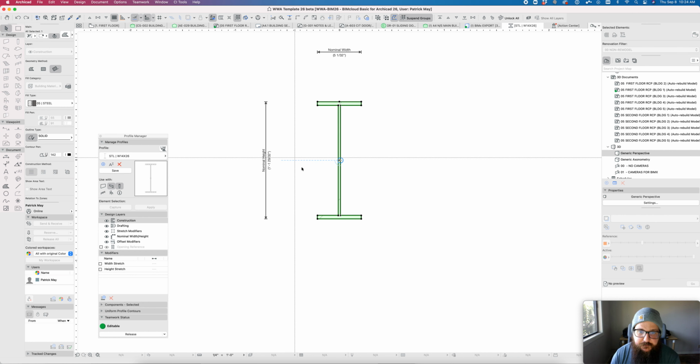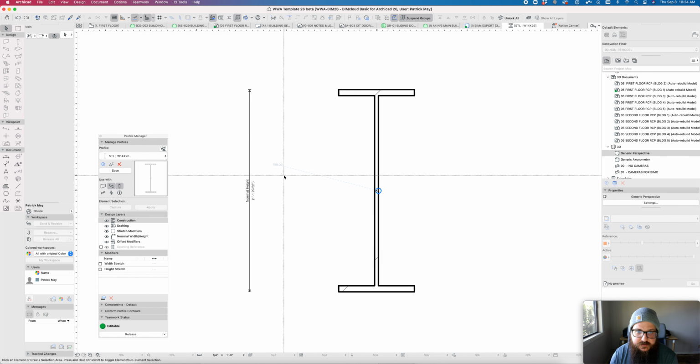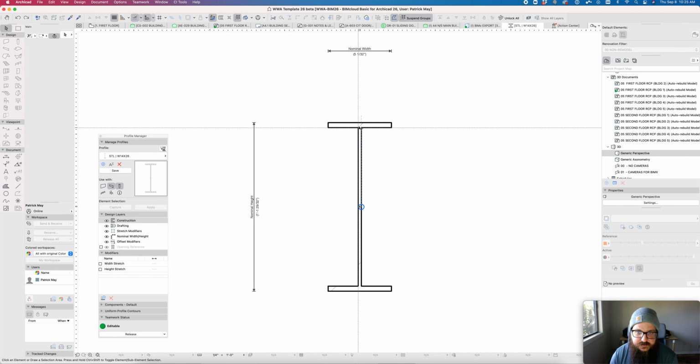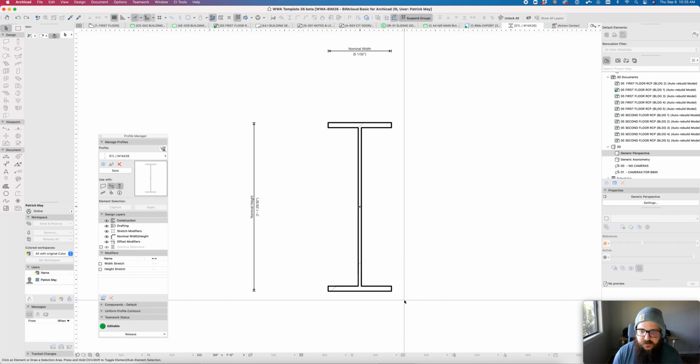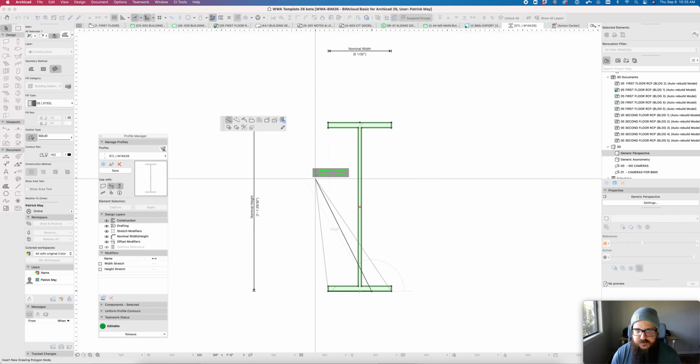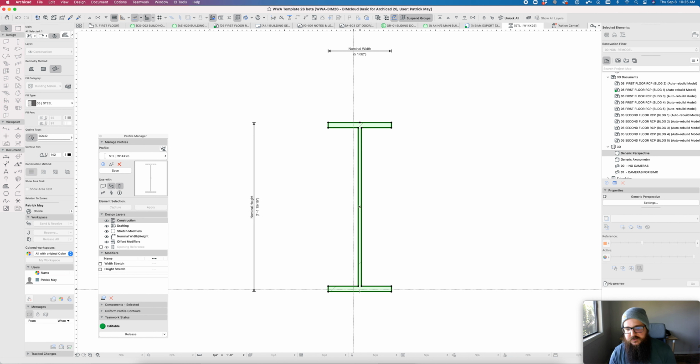The other thing to note here is that the standard heights for a lot of these steel profiles include 32nds and 64ths. So if you're placing this beam to align to a top plate, just know if you're dimensioning the bottom of that beam, you're going to see 32nds pop up in your dimensions on the sections and elevations. So we do have to be careful about where we're snapping to. If you see 64ths, it's not an uncommon practice to stretch this down a 64th or 32nd of an inch. It really depends on the level of precision you're going to be dimensioning to.